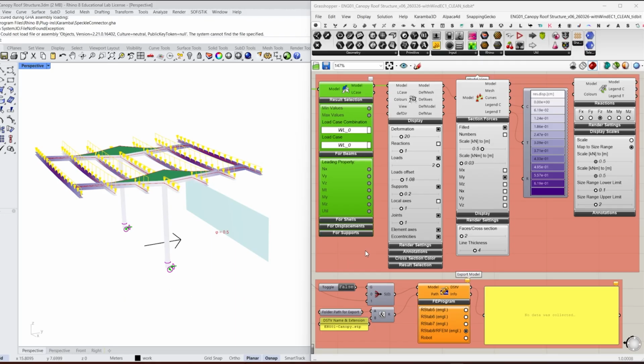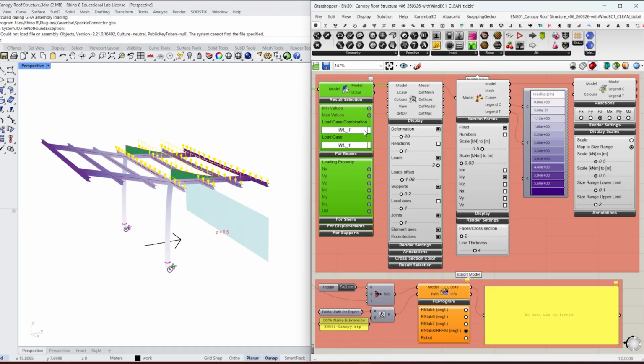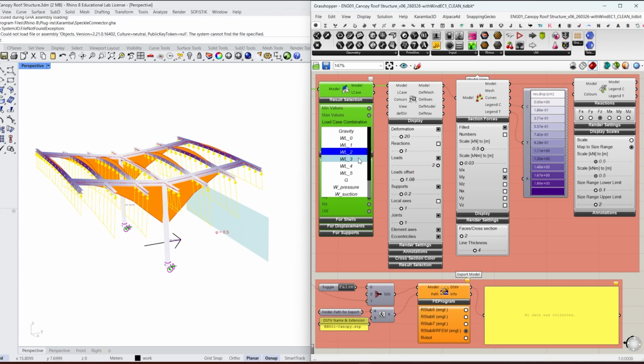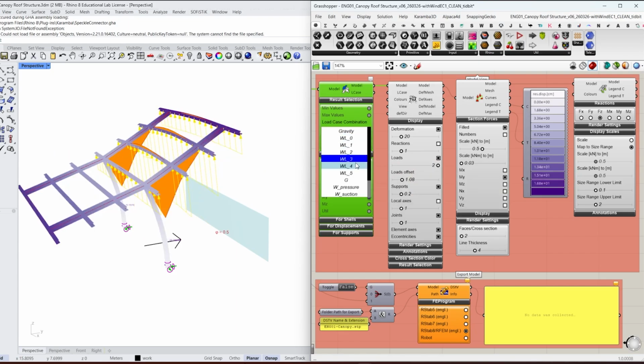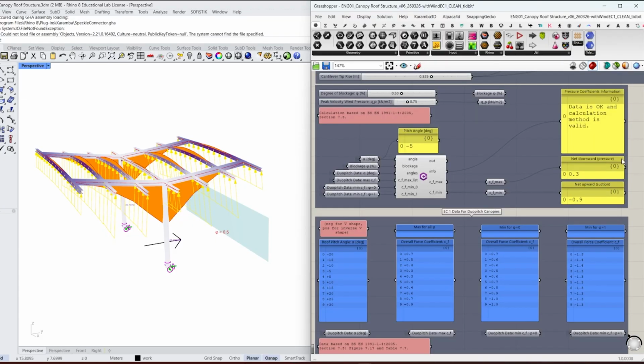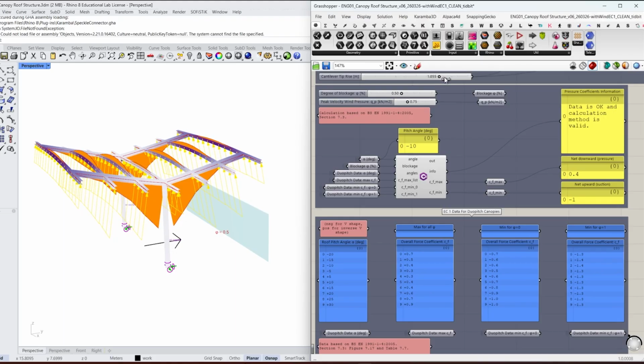This video specifically covers wind load definition based on Eurocode 1, Part 1.4, General Actions, Wind Actions, and we're looking at section 7.3, Canopy Roofs. Canopies are defined as the roof of a structure that has no permanent walls, and it is applicable to structures such as carports, gas stations, shading structures, and so on. Finally, we're only talking about a specific type of canopy, dual-pitch canopies.